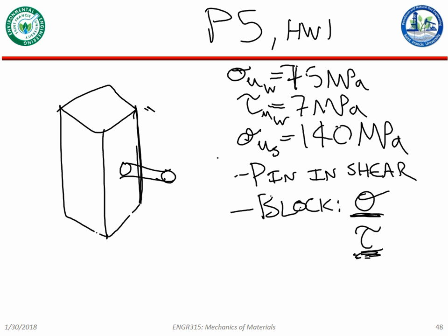Bearing stress would be, what if this pin rips straight out through the bottom of the block? You're pulling on the pin. What if by pulling on the pin, you just rip that sucker right out of the block? It just pulled through all that material, which is right underneath of it.